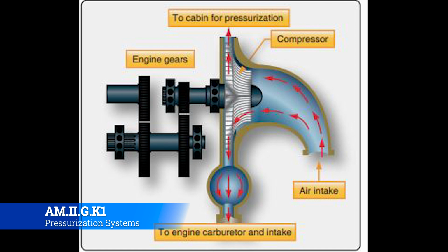Okay, so what are the sources of pressurized air? Let's start off with our reciprocating engines. There are three basic ways to pressurize a recip aircraft: a supercharger, a turbocharger, or an engine-driven compressor. Like I said, that 206 we had in the other day has a turbocharger on it, and it works just like this. The engine turns the turbocharger to bring in air and compress it and push it into the cylinders, which we're going to get to when we get to powerplant. One ancillary thing it can do is take that same pressurized air and force it into the cabin, and that will supply pressurized air.